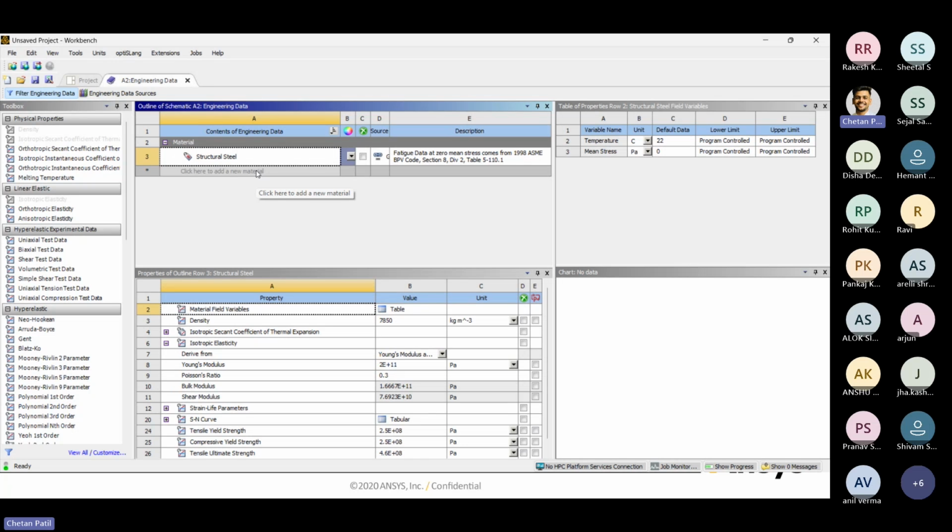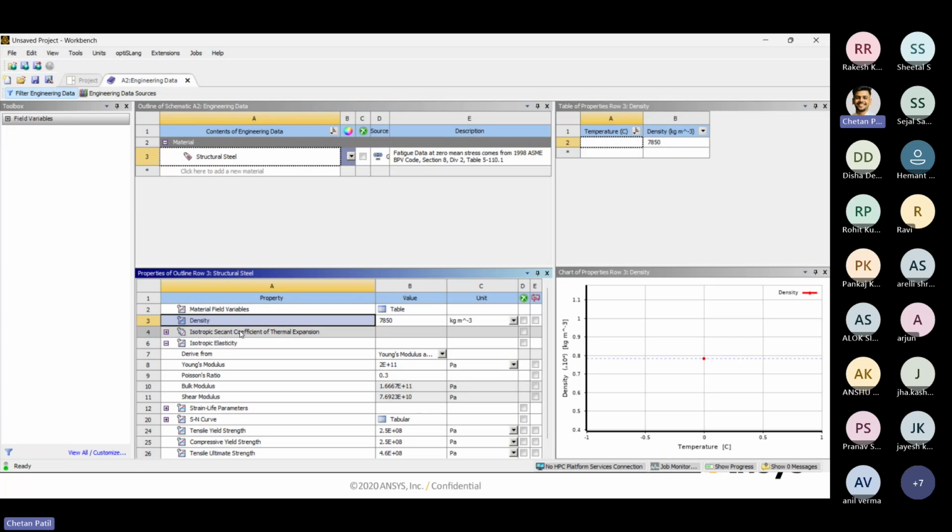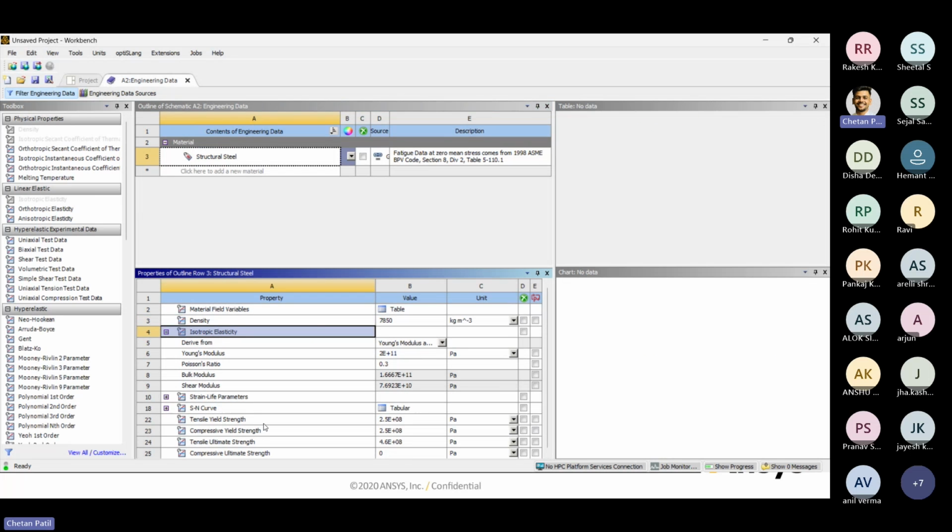If the body is too stiff and doesn't undergo easy deformations, then it will take more time and more force, and I don't even know what amount of force might be required to displace the body in such a situation. So what I can do over here is delete some of the properties which are not required for my simulation.